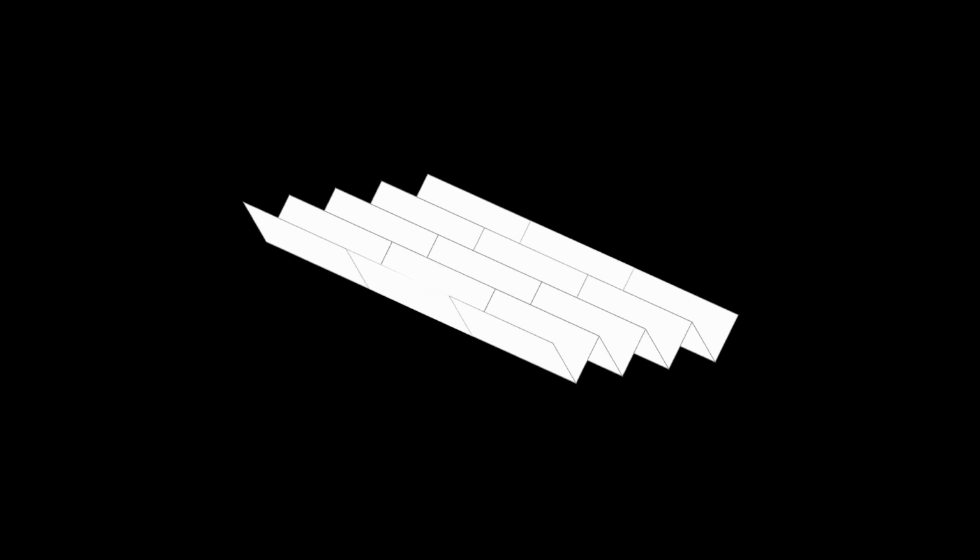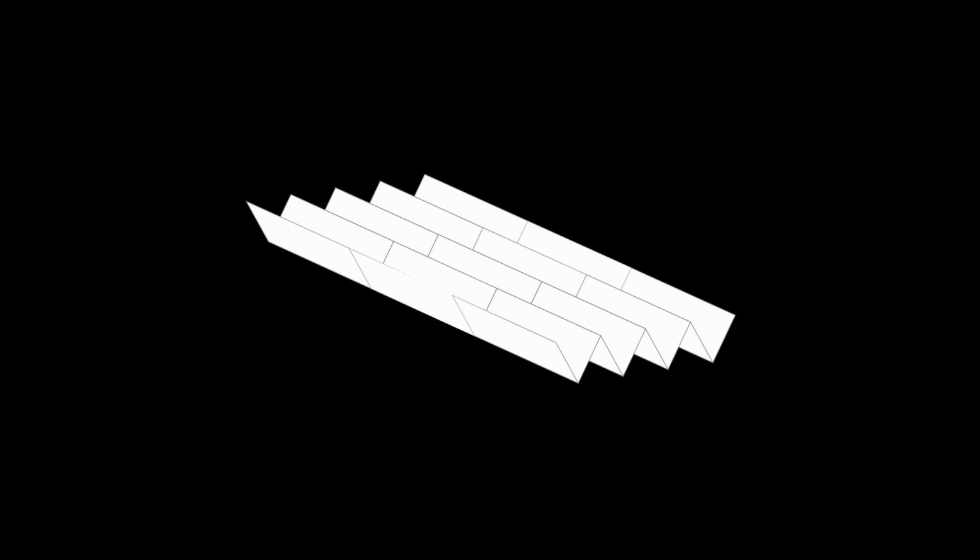When we take a look at the cross-section of the flat piece of paper, we can tell quite easily that its second moment of area is very small because all the material is clustered close to the neutral plane. This makes it bend easily and fall between the chairs. However, when we add the zigzag folds to paper, more of the material is moved further away from the neutral axis, so the second moment of area gets way bigger. The paper is therefore able to resist bending, so it doesn't fall between the chairs. The same principle is used in corrugated cardboard and corrugated iron to increase their rigidity.